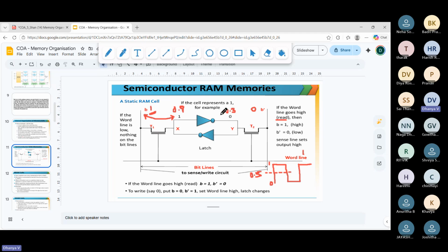So in reality, it is some odd values like these. So how will we read it? We have to read this 1 to your B, no? So there's something called an amplifier that actually reads this. It reads the difference between these two, and then it concludes that a high value is stored. So 0.6 is greater than 0.5, the threshold value, so it is a high value. It will conclude that a high value is stored.